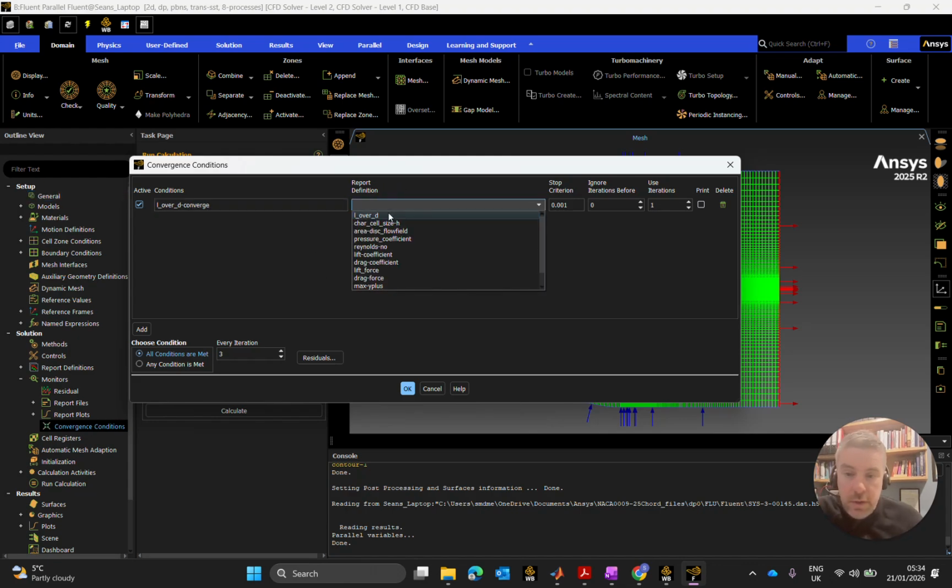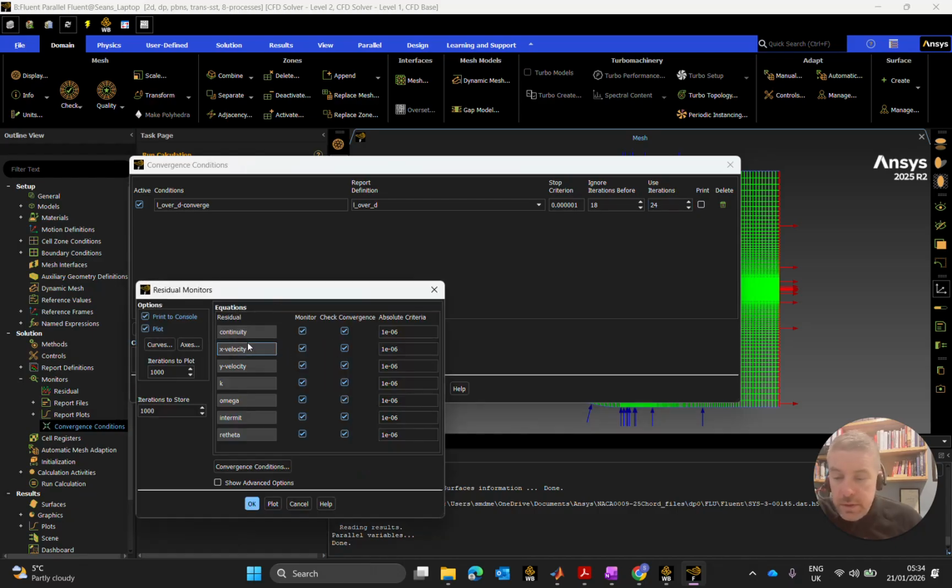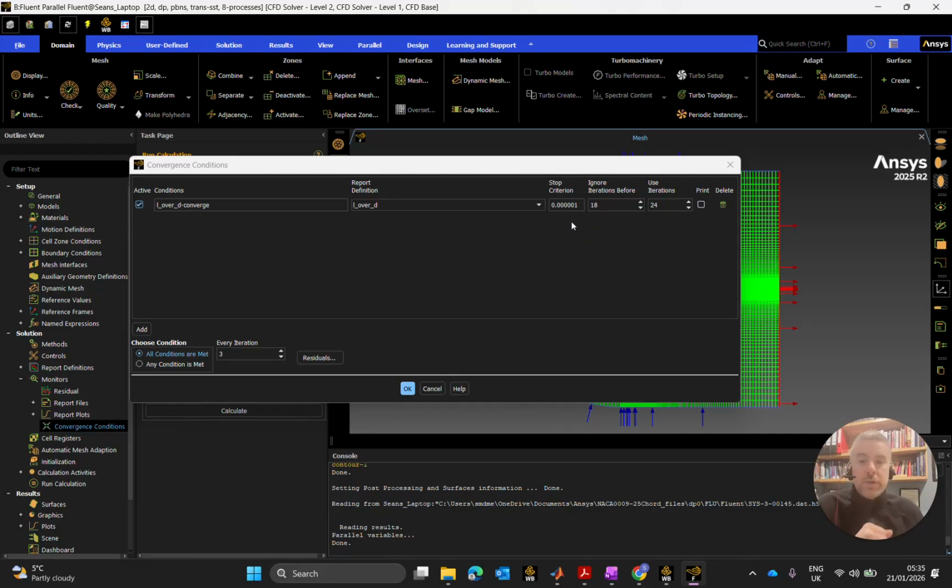Converge, that's L over D, stop criterion. Okay, let's make it a wee bit tighter for it to converge. Again, I'm going to ignore the first 18. I'm going to run at 24. Check every 3. Good enough. And let's just double check our residuals, which are here. So there's our continuity, our 2 momentum, K, omega, 2 turbulence, and 2 transition equations, iterations 1,000. Yeah, okay, grand. The residuals are always going to be checked as a convergence criteria.